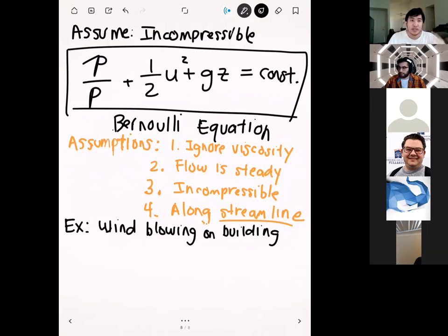So for our purposes, when we say compressible, that means that the density can change, because we can compress the air into a smaller space or expand it. But incompressible means that the density is not going to change. Like if you take a water balloon and squish it as much as you want, it might deform in different ways, but it's never going to change its volume. And that's basically what it means to be incompressible. Does that make it a little bit more clear on what that means? Yeah, okay.